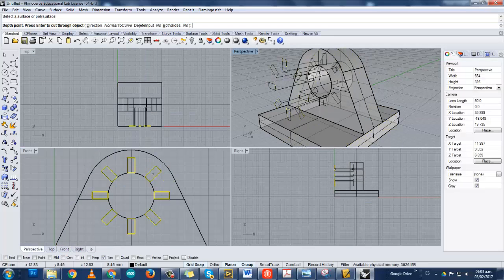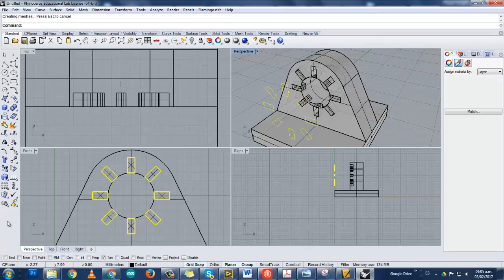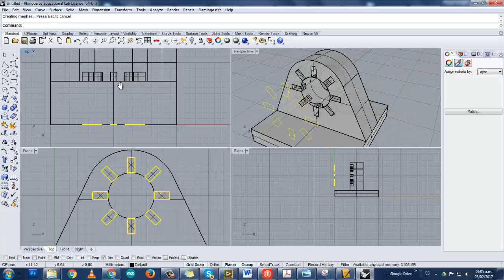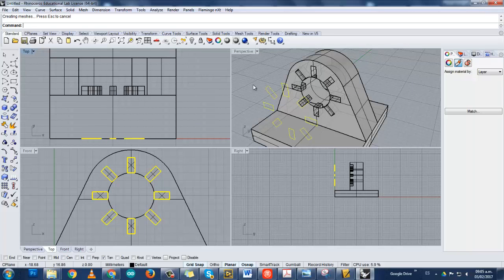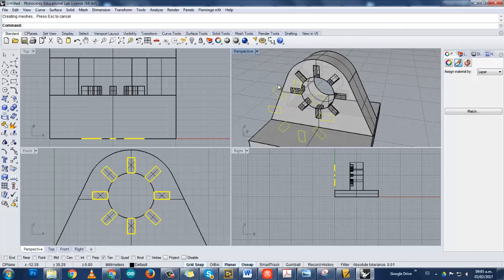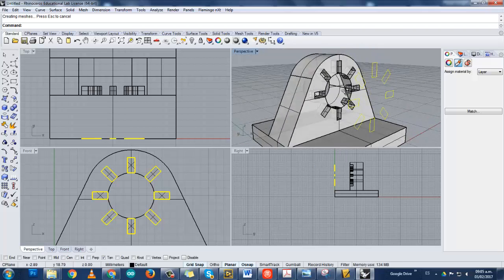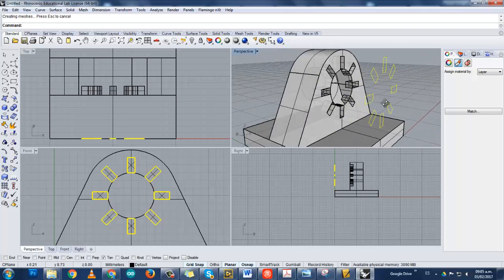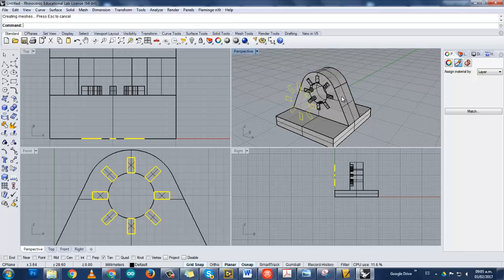I'm going to make some holes right here. Okay, so it looks kind of like this. Make sure that you only enter 2 millimeters inside. It doesn't go right across. That way the other object that I make actually goes inside this small portion. Okay, so that is pretty much how polar arrays work.